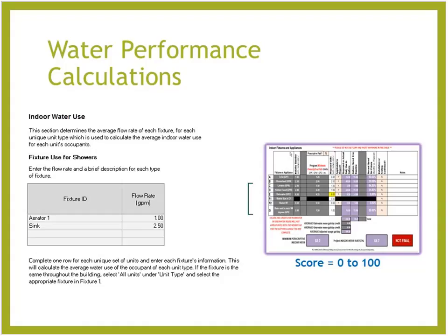what kind of anticipated water use the home is going to have, and then ideally what kind of anticipated water cost, similar to the idea of designing for clients an energy cost and then optimizing it, it is the same for water. And so then you can tweak certain things with your clients to say, we really want to hit these water targets, but we're not going to settle for lower flow showers or whatever. You can work with them to tweak some of these numbers in different areas to find the water offsets in other ways, similar to what you would do on an energy score.